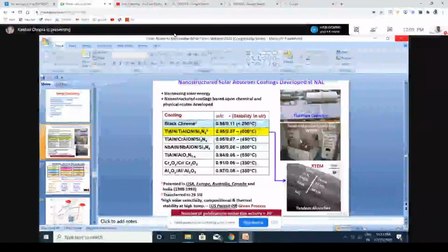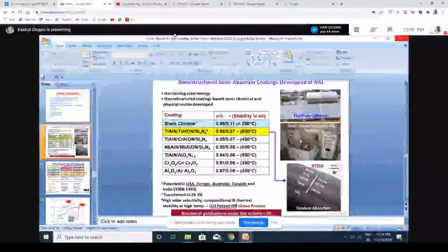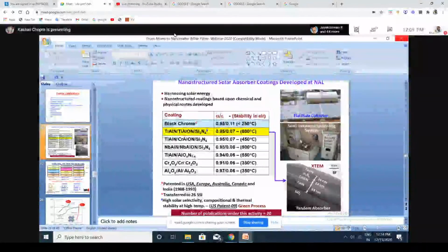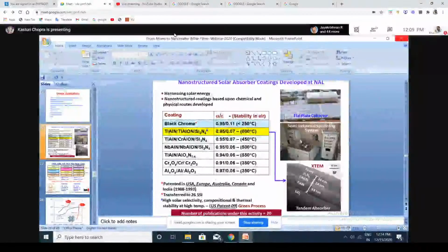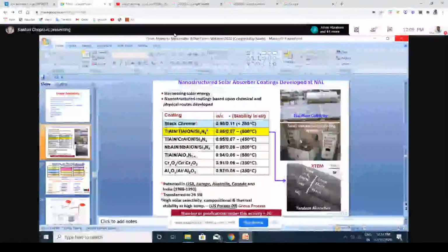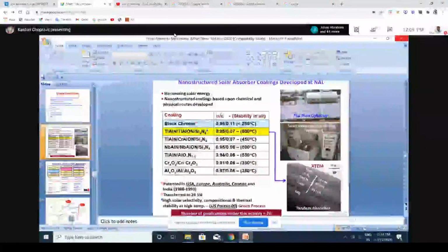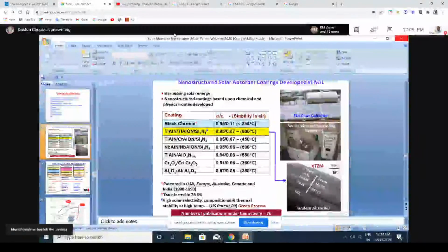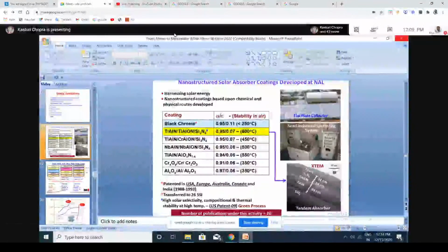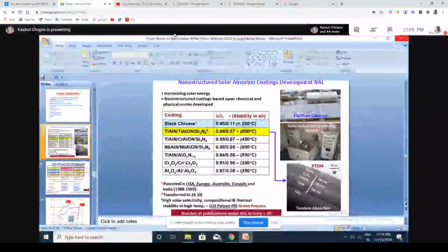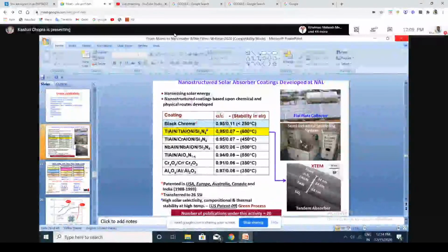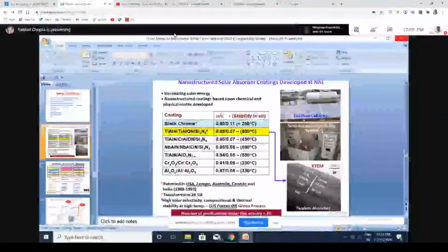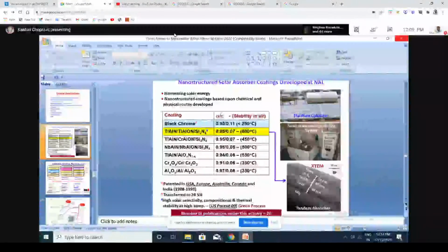Again, our student here has done that. Okay, just to show you to what extreme level can we go. In fact, he's not happy. Nobody's happy. They want to go further. For example, if you have titanium aluminum nitride on titanium aluminum oxynitride on silicon nitride, now you can see here how all the three layers have their own functions. Okay, so you can absorb 95% of the solar spectrum in it, and it goes to temperatures up to 600 degrees centigrade.